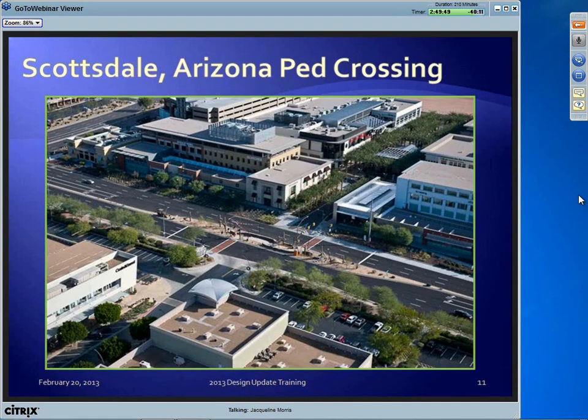What's really neat about this crosswalk is the timing on the signal, and it's a HAWK signal. When they start, hopefully you can see my pointer on the screen, when they start to make this crossing, they're detected, and then this signal over here is cued to start by the time they've negotiated this linear piece in the median.